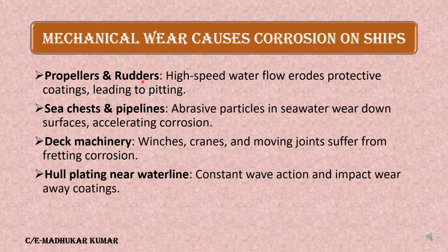What are the parts where you will find this mechanical wear corrosion? Propeller and rudder, basically where there are moving parts. High speed water flow erodes the protective coating, leading to pitting. Sea chests and the pipelines.